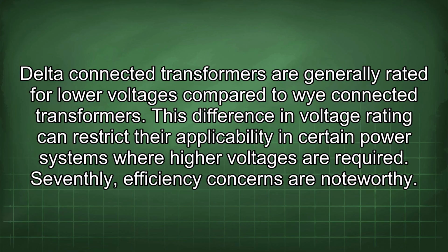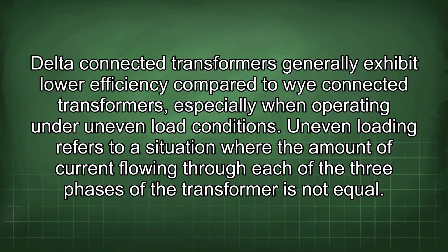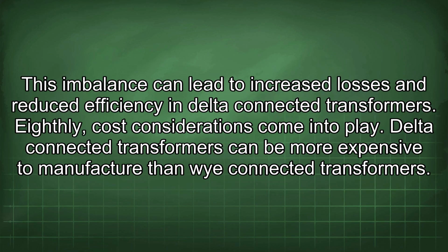Seventhly, efficiency concerns are noteworthy. Delta-connected transformers generally exhibit lower efficiency compared to Y-connected transformers, especially when operating under uneven load conditions. Uneven loading refers to a situation where the amount of current flowing through each of the three phases of the transformer is not equal. This imbalance can lead to increased losses and reduced efficiency in delta-connected transformers.